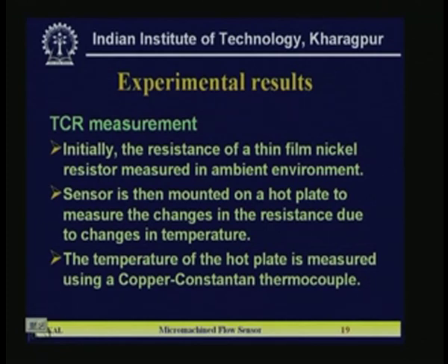So, first is the temperature coefficient of resistance measurement. There, what you have to do, for the thin film nickel resistance, all the measurements are done in an ambient environment at room temperature. For TCR you do not need the fluid flow. TCR means temperature coefficient of resistance: you have to increase the temperature of that particular film and measure the resistance change. Okay. So, that is the objective.